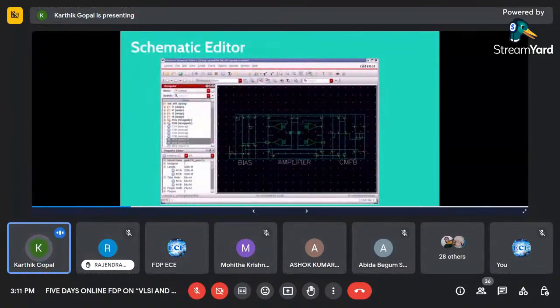And this is how the schematic editor looks like, the Cadence schematic editor in the industry, what we do. So this is one of the circuits which I have worked on. Here you can edit at the transistor level, and there is a symbol which you may see, like an op amp symbol. So that is a hierarchy. So we can build multiple hierarchies as a schematic, and we can go inside.